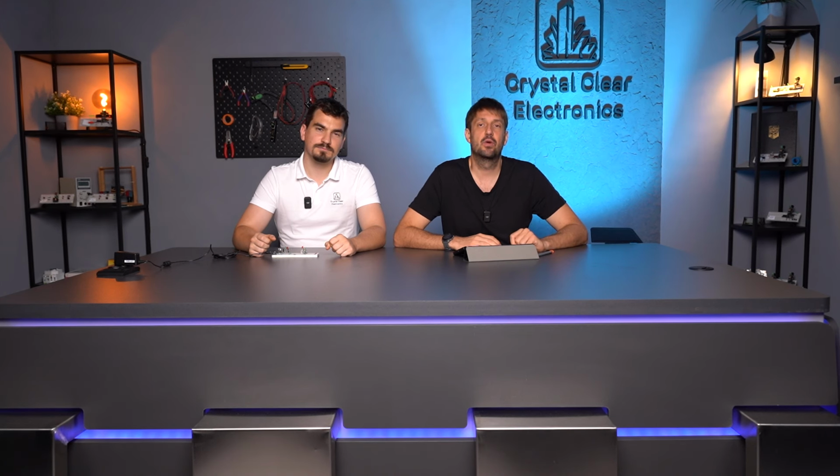Initially, the voltage of the capacitor C1 is 0 volts. When the power supply is connected, the supply voltage can be measured on the IC output, and the LED is on, since the voltage on the trig pin is lower than 1/3 of the supply voltage, hereinafter referred to as 4 volts, and the S input of the flip-flop is 1.